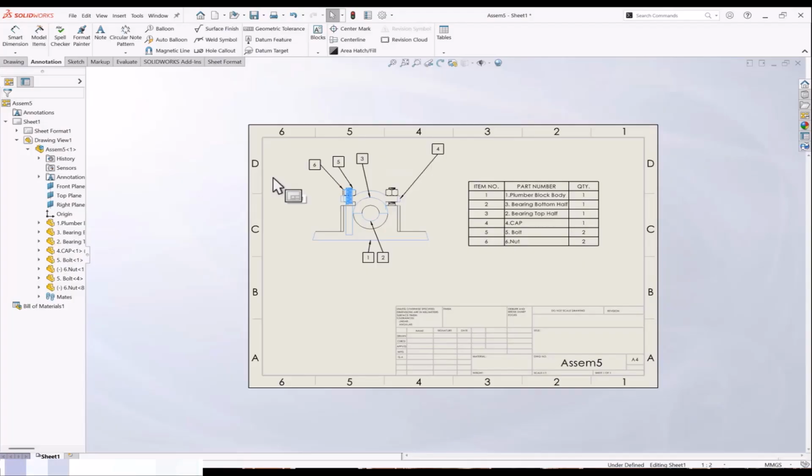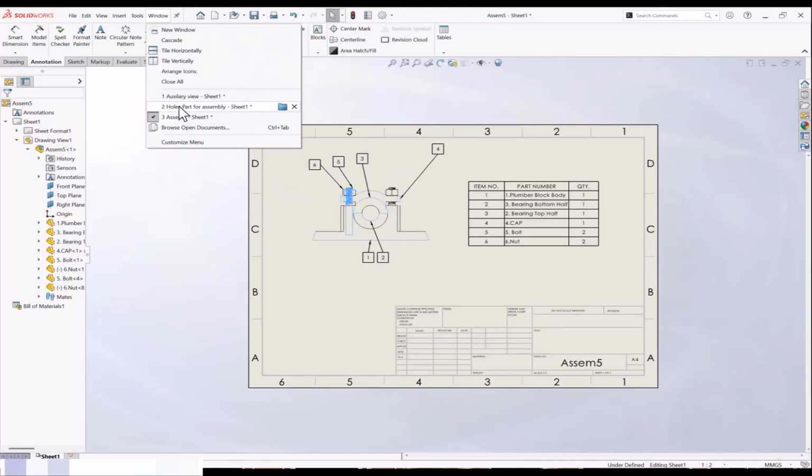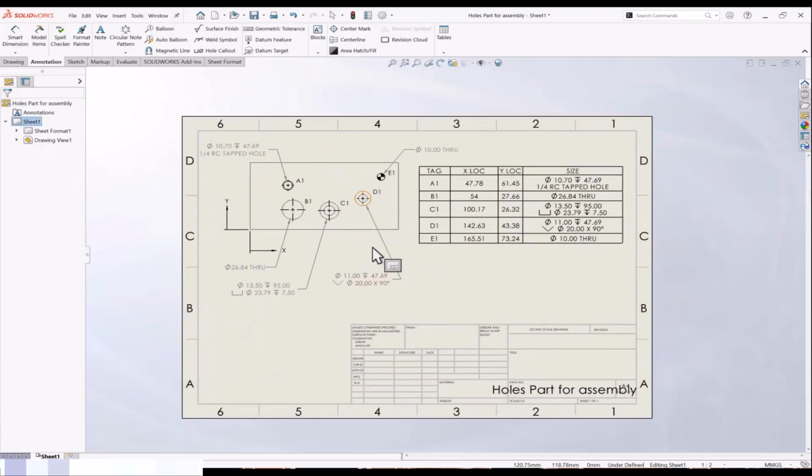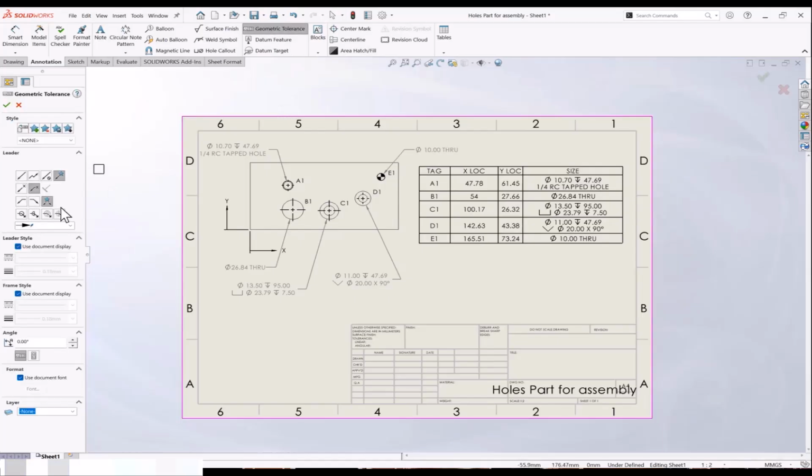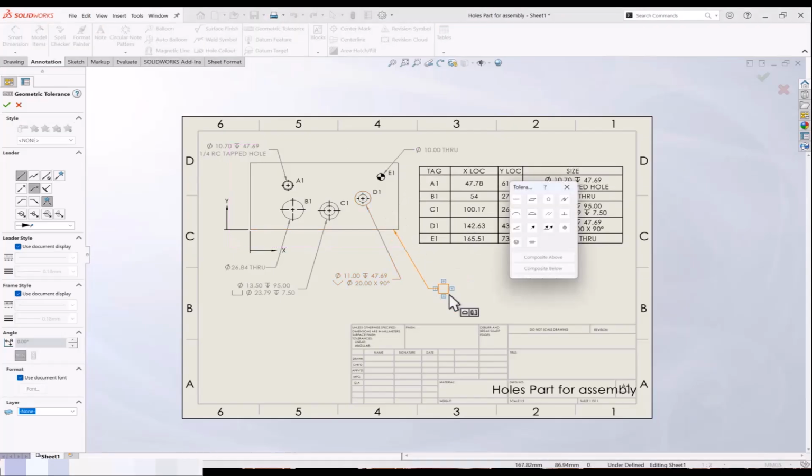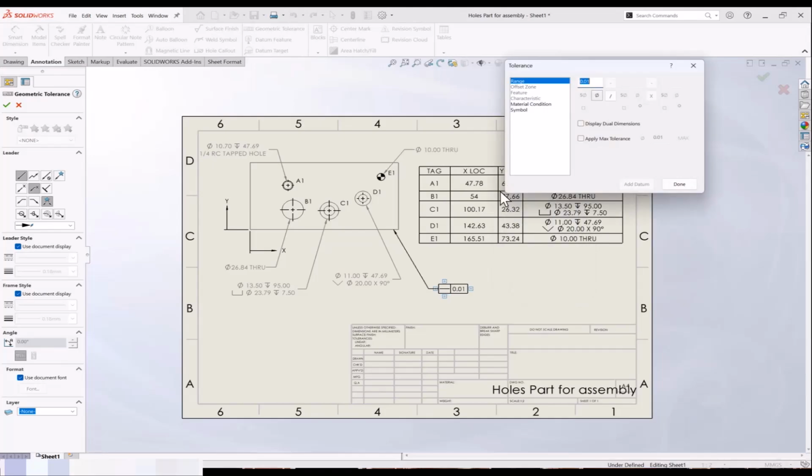Now, if you are making any drawing where you want to define any geometrical representation details, you can go to geometrical tolerances. So what type of tolerance you have in your parts for that model you're representing, you just mark that. So I said this is a flat model. The tolerance range at 0.01, and any other details you want, you define that. So material condition, you can define if it's a maximum material condition, least material condition.